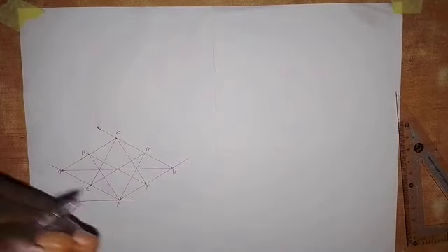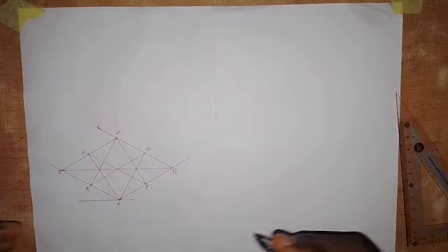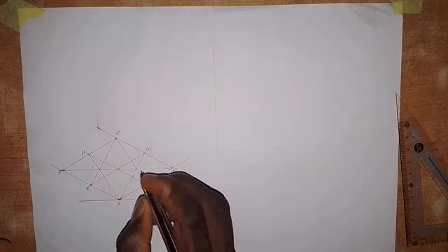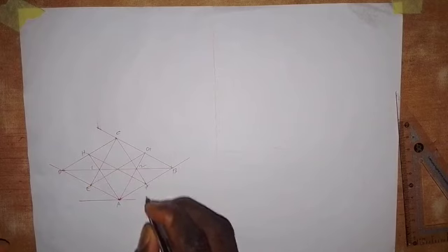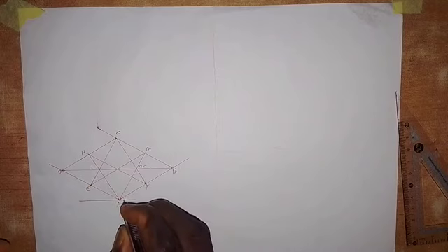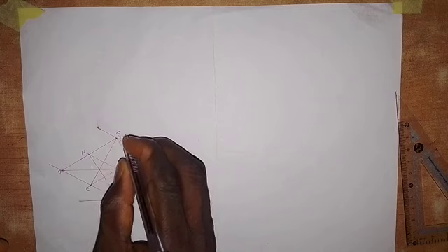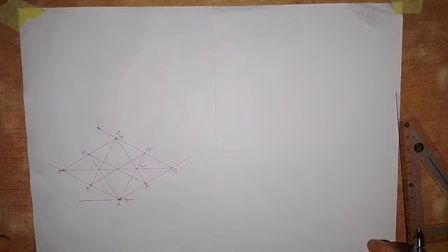Now, the four centers that we are using to construct the isometric circle: we have this point here to be center 1. We have this point here to be center 2. Then we can take this point A as center 3, while point C is center 4. So we have these four points. These are the four centers that we are going to use to construct the isometric circle.